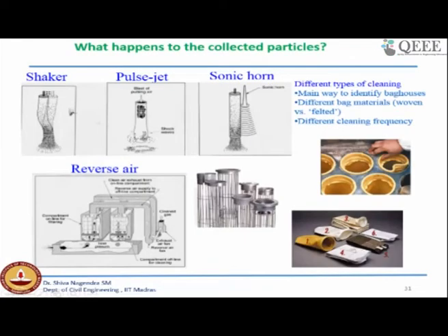See the bag filters when you design. Okay, so you will come across a number of bag filters. You can arrange them in different shapes, either rectangular or square, depending on the requirement. So you can identify the number of bags required. You can design the number of bags required for each compartment, and then keep one compartment as an extra to use for cleaning purposes.